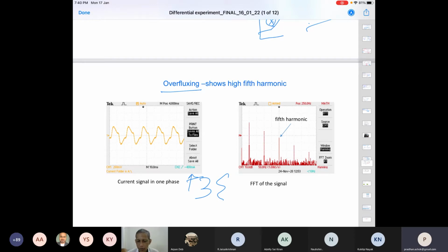If the voltage becomes very high, then the corresponding overfluxing issue arises, and the current becomes significantly high, much higher than the normal current. Where will it flow? One side only. So the differential current again becomes high. So again, considering the percentage bias, it will be above this characteristic. That's the problem. Therefore, to avoid that, this must go to restraint.